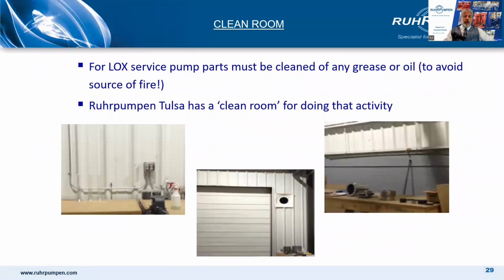Any grease or oil coming into contact with oxygen is a potential fire risk or explosion risk. Pump factories are not traditionally oil and grease-free environments, so the Sulzer factory has a clean room for pump assembly of LOX pumps. It's air-conditioned and a positive pressure system, so no factory air gets inside the clean room.